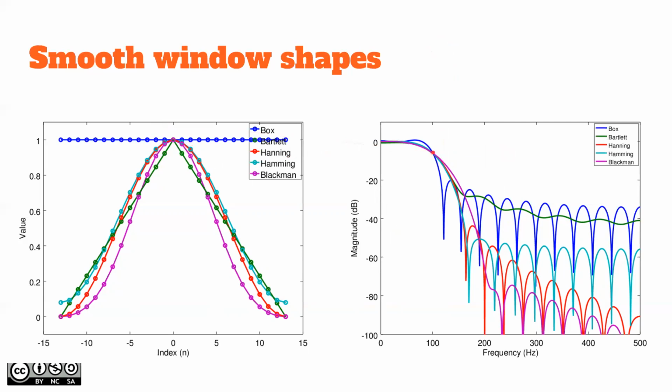as you can see, all of them have the minus 30 dB point exactly at the same point, as it should be. This is the window shape, whereas the sinc function defines the cutoff frequency. So practically now we have a method to control the stop band attenuation based on what the requirement is.